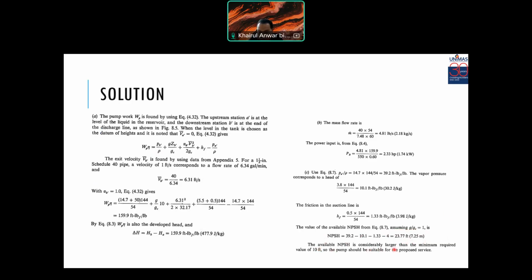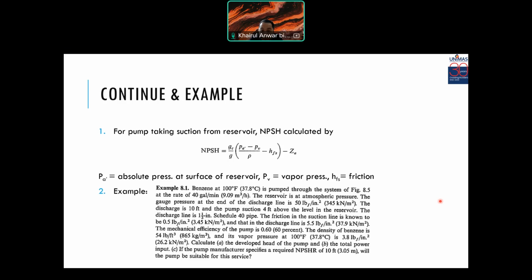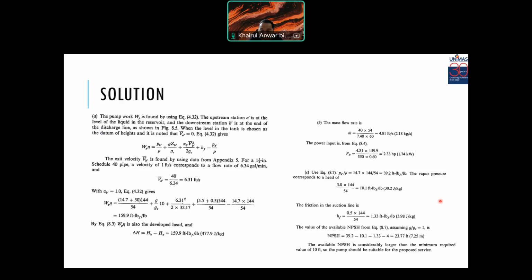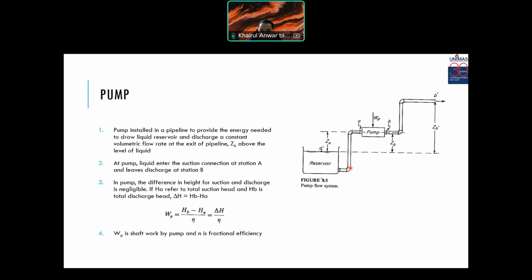The available NPSH is larger than the minimum required value of 10 feet, so the pump would be suitable for the purpose. So the minimum required NPSH is 10 feet. If the pump can produce more, it's suitable for the purpose. So the service here is to transfer liquid using the pump to here, ZB.